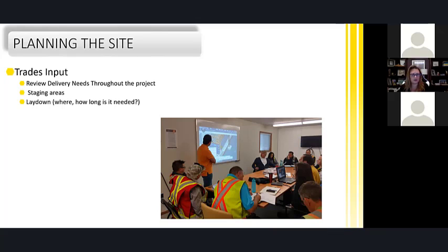So we sit down with our superintendents and, more importantly, our trade superintendents, and we go through everybody's input from the form worker, the mechanical trades, the electrical trades, and identify how we're going to service the site. The size of crane is not necessarily determined by the largest item. It's interesting because the largest item often is our core boxes. Recently, we just determined there was a small but very heavy piece of mechanical equipment that determined our crane sizes.